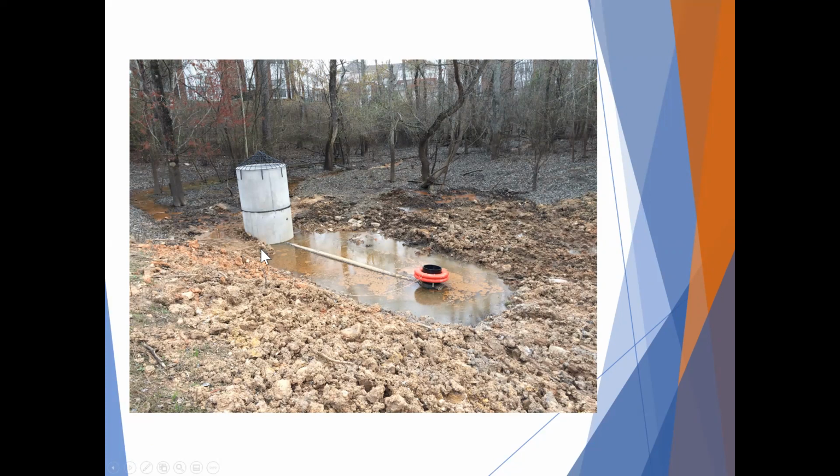We put in an outlet structure, a riser, and then we put in a skimmer. That was a challenge because the City of Charlotte's design manual said point blank that skimmers cannot be used for post-construction. They put that in when they were familiar with the Faircloth and the PVC model. So we actually had to meet with the City of Charlotte, take them our skimmer, let them beat on it, and see that it's an HDPE product, very durable, UV resistant. They said, okay, you can use that permanently. So we designed the site to do that.